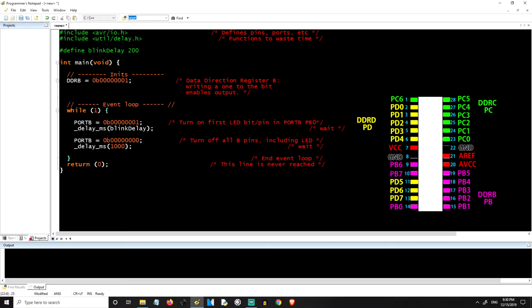And then we need to close the doors on our way out. So for the loop, we have this open bracket and this closed bracket, and then we have return 0 and a semicolon. This is just good practice in general for C programs. For normal C programs, like for a computer, you have to have this. It means you're just ending the program. You're not getting anything in return. It just ends that loop. Just write it, just follow it. You don't have to worry about it. Just include it. And then you have the final bracket like I showed you before. So everything looks clean, and we are almost ready to flash the program to our chip.